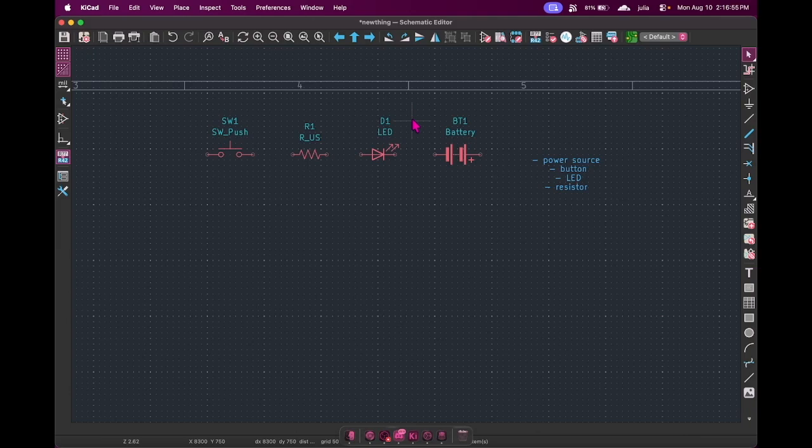When you get to the actual PCB layout, there's this thing called the ground plane, and that's basically anything that goes to ground. It's not gonna have just a single trace. It's gonna have a whole net. I think you know this because you tried making a PCB that one time and I told you about ground planes. Ground planes kind of cover the whole PCB, and wherever you're not having a trace, there's gonna be a ground plane.